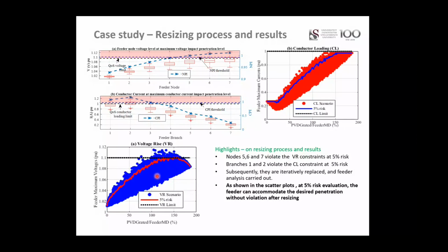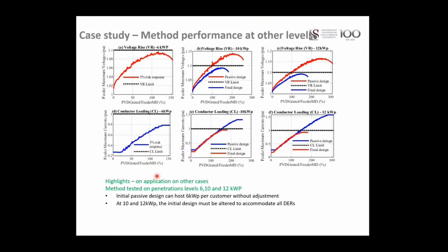Come again? I think what Solani is trying to point out, and it's quite a good point, is that your most adverse cases of voltage rise may occur when your network is lightly loaded, and yet you have full contribution of these DER systems.